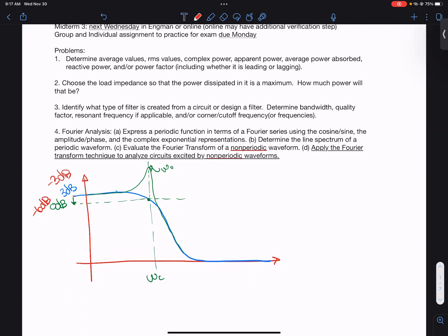What shape is this? In this case, it would be a low pass filter. And then to find omega C by measuring it on the graph, you would have either of those two situations, where it would either be at the omega naught because it's got a lot of resonance and a high Q, or it would be able to be measured easily off the 3 dB less than it.